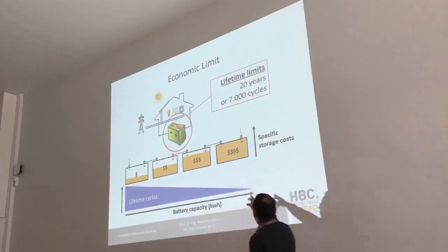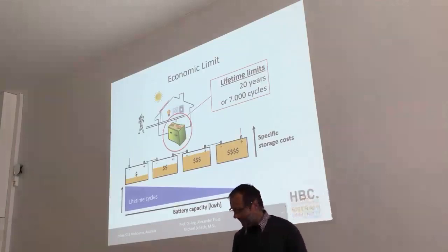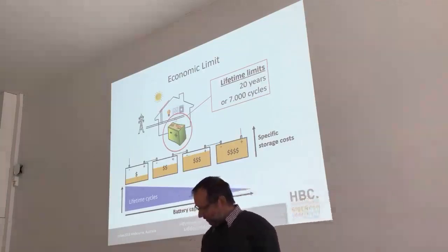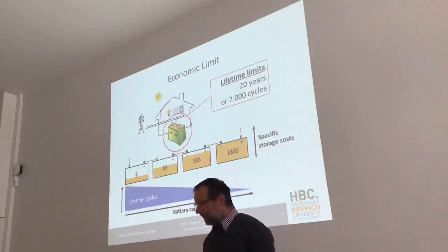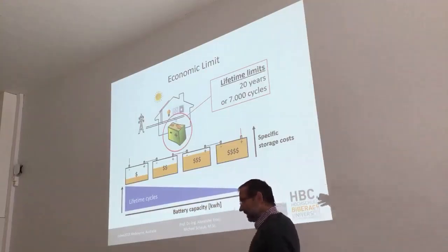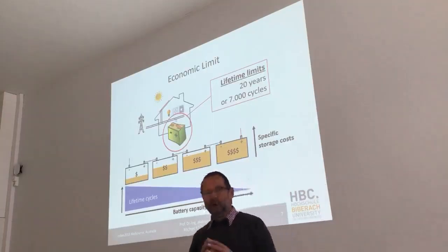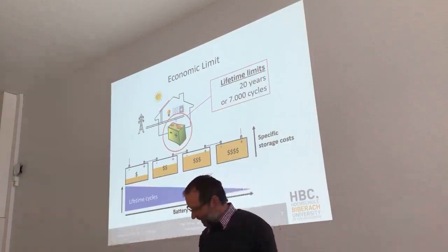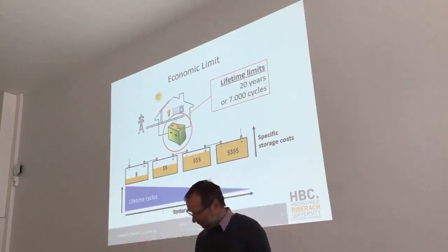That means how often the last battery cell is charged during its lifetime, in order to assess the economic viability of the battery capacity. As the charging cycles of the whole battery, and especially of the last battery extension, decrease with a growing storage capacity, the specific storage costs grow with larger batteries too.